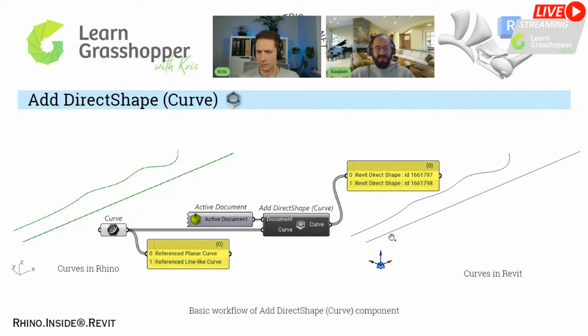I would go there and rotate that plan based on this curve, because I needed a specific angle at which I wanted to rotate it. This line was giving me the reference. When I had rotated my plan, I would delete this object. After that, no one can see these objects in Revit. So that's how I have used these DirectShapes in my workflows.